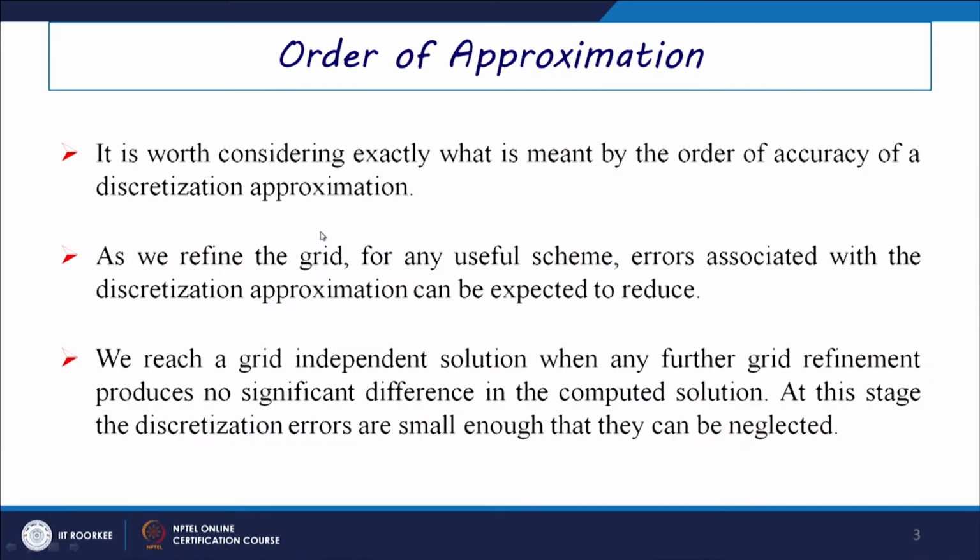So, when we reach this grid independent solution, this means that for further grid refinement, we will not find any significant difference in the solution process, and at this stage the discretization errors are small enough that they can be neglected.